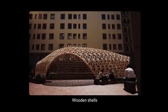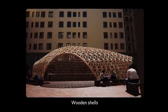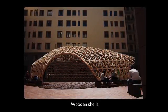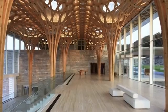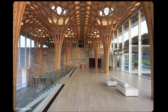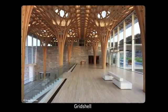Another old construction material with low carbon footprint is wood. Wood comes from trees and trees are linear. Engineers have been building vaults made out of a grid of wooden lats. Before, with reinforced concrete and Catalan vaulting, the vault surfaces were continuous. This vault now has holes. This is a new kind of structure, which we call a grid shell.